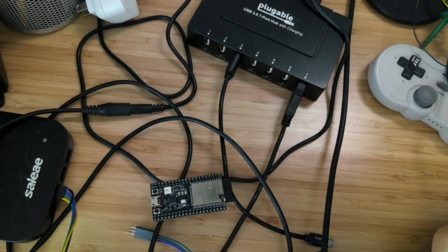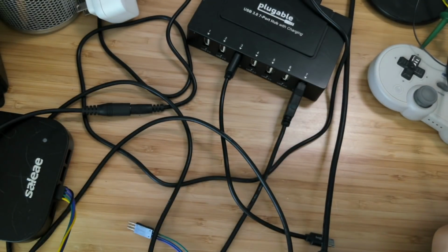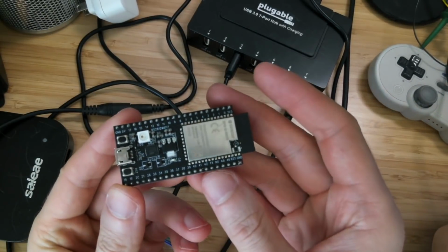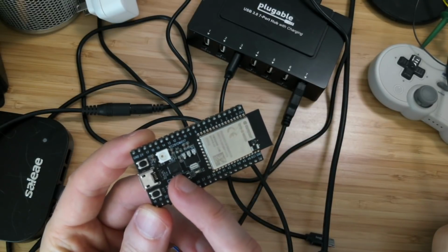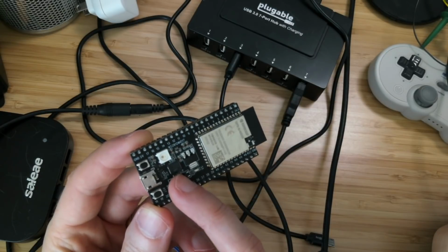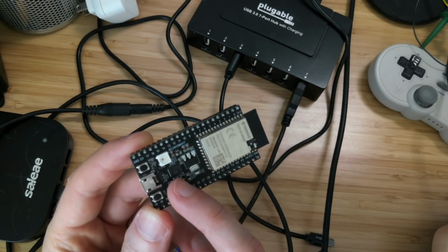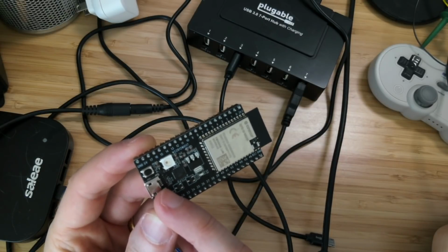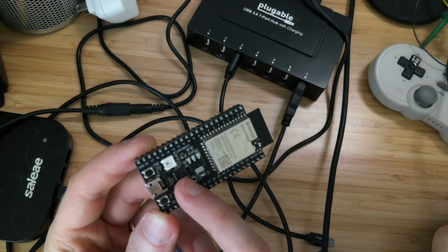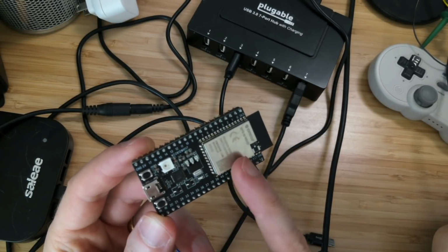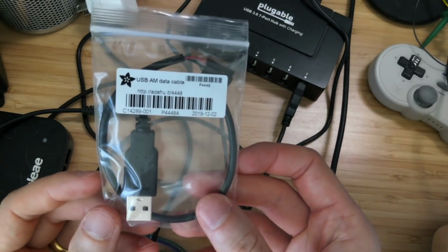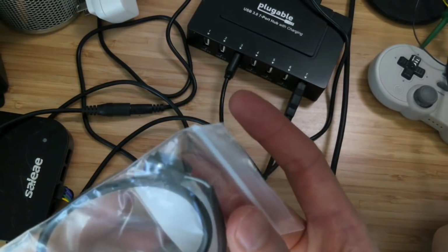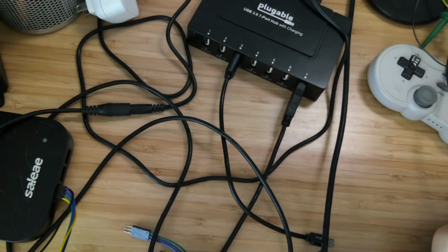And then the thing here is what I was talking about. The chat's distracting me. So on this board, it might be a little blurry, but that's okay. There is this conversion chip that I was talking about that is common on the other ESPs, the ESP32 and the 8266. So this dev board is actually also doing that USB to UART conversion. But they did break out the USB pins. So what I have here to test the native USB is a male data cable, which has just pin headers on one end. So we'll have to triple check our wiring on that when we start to test it.